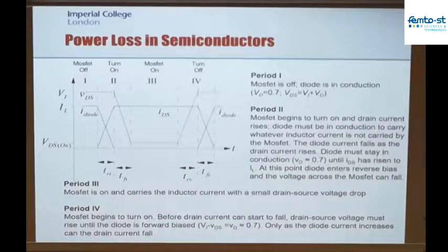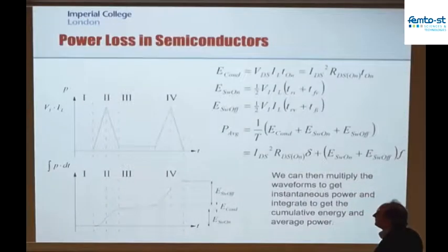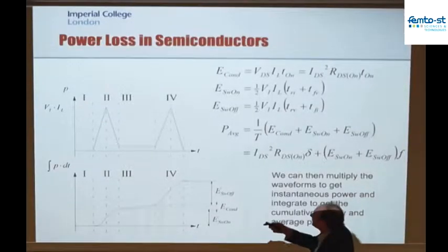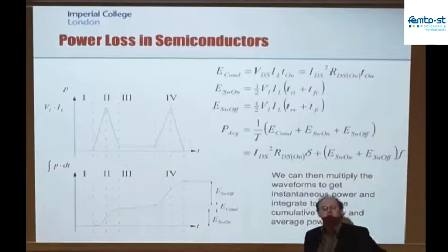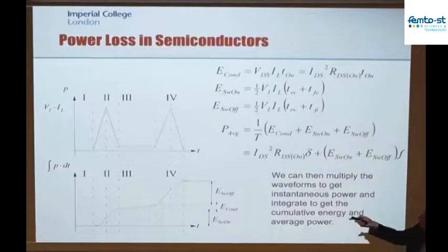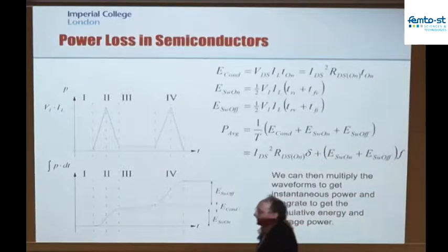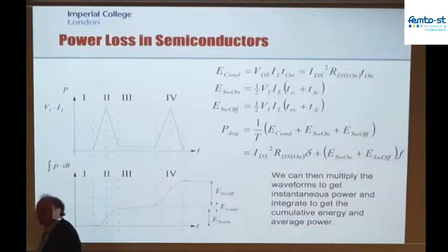So there's an inherent switching loss associated with these types of power converter, which effectively means that as I switch the device on, I get a sudden burst of energy loss, then a small amount of loss continuously as the transistor is conducting, but it's not a perfect conductor. It's got a little bit of resistance, so there's a little bit of loss there, and then when I turn it off again, I get another blip of power loss. So this is not quite what I was telling you originally, where this is theoretically an infinite efficiency circuit. It's fundamental now to the way that current will translate from one component to another, that there is a loss associated with that switching mechanism.